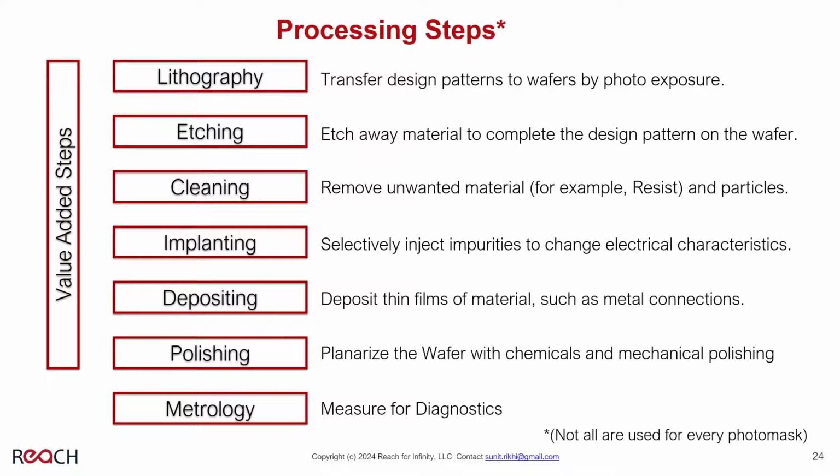And then, of course, there is the metrology. Metrology is tools that measure to help you diagnose what's going on. Now, if you notice, I've marked all of the steps except for metrology as what we call value-added steps. That's because they do something to the wafer. Metrology doesn't do anything to the wafer. And it is the most hated evil.